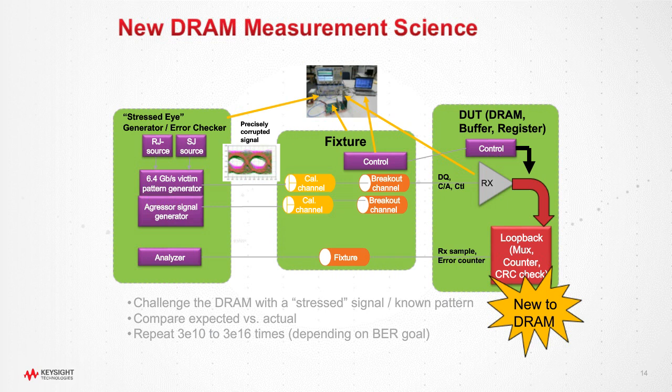And it's something that is important not only to make the measurement, but also because it involves connections at one of the most design and parasitic intensive parts of the system, which is the receiver and the PHY. So conceptually, it's a pretty simple thing to do, is to add loopback. In practice, it requires a fair amount of preparation and work. But there really isn't going to be any other way to characterize a design and verify it against the spec without this kind of receiver testing.